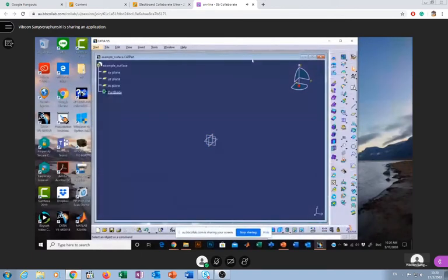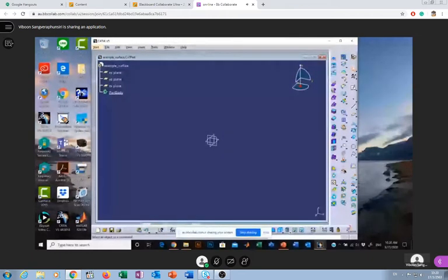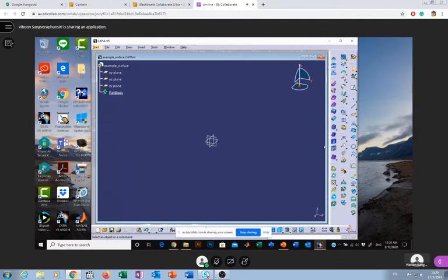Look at this one. If you want to generate a surface based on solid modeling style, as I mentioned last week, you have extrusion here, you have offset here, and you have multi-section here. Last week I showed you the very powerful multi-section. The number of points of each section doesn't have to be the same, which is more constrained in solid modeling compared to this multi-section surface of surface modeling.